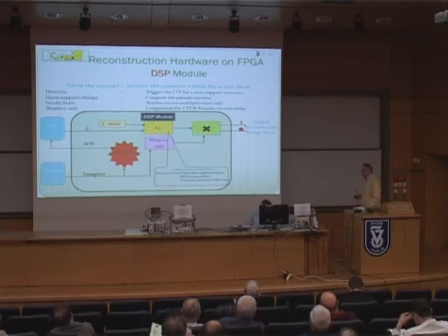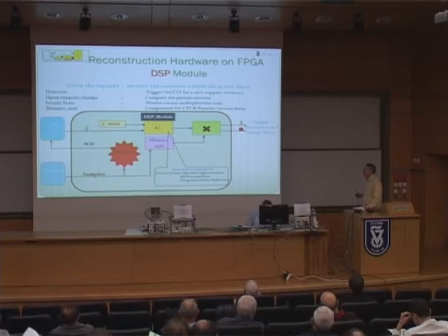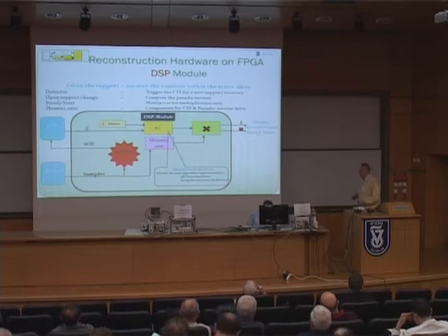It has about 250 samples, so that is the total latency we need from the beginning. We said we need 70 pulses, and then the calculation, it's about 250 samples which we store in the memory. So we have a delay between the beginning and the output of about 200 samples at 20 megahertz.